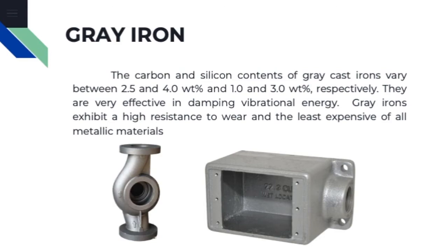It is also used for housings where the stiffness of the components is more important than its tensile strength, such as internal combustion engine, cylinder blocks, pump housings, valve bodies, electrical boxes, and decorative casting. So here, ito po yung pump housings and yung electrical box.